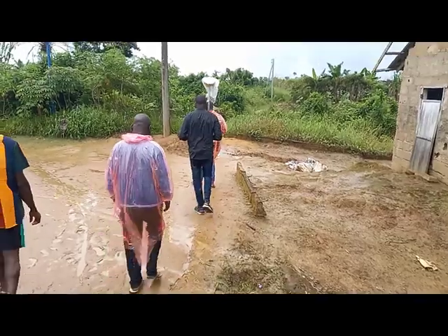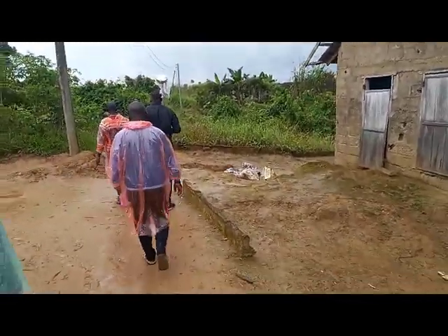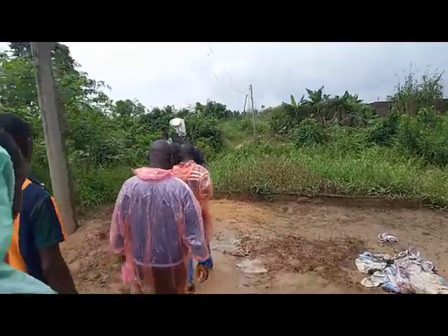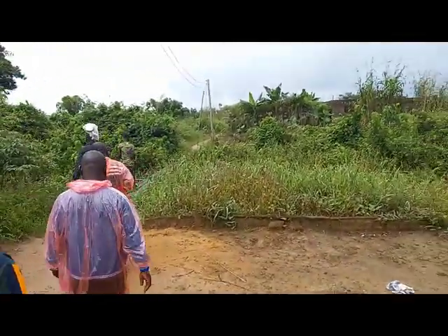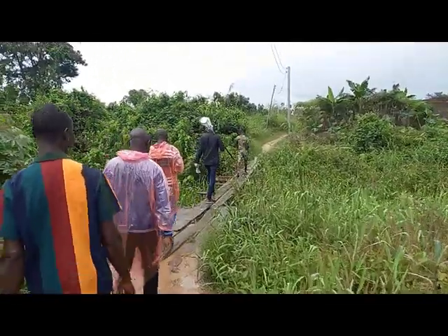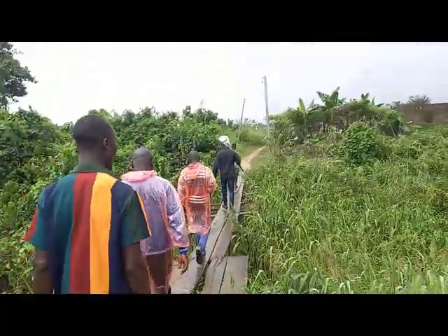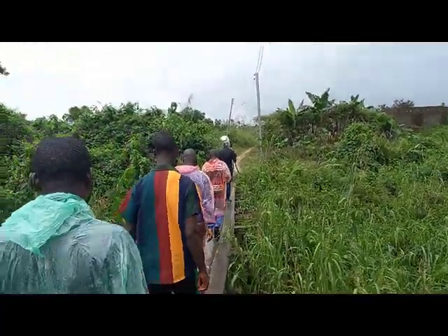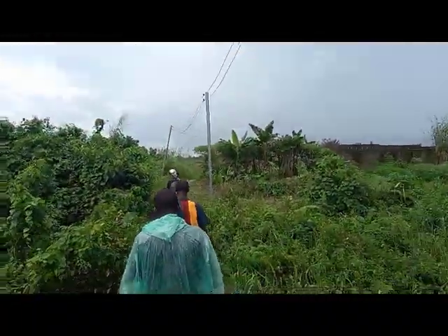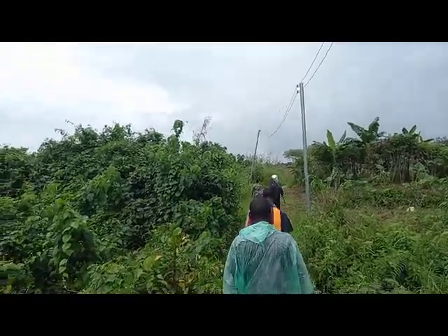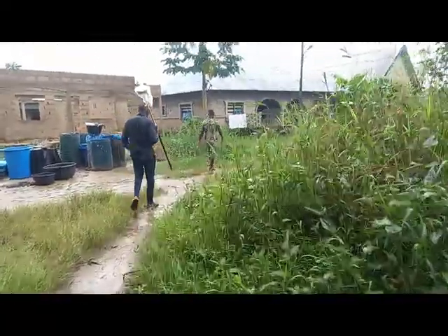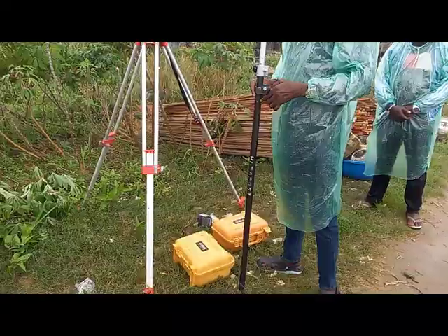So you see here when we're taking points within the community. Once you get to certain places, there are different distances that you can be taking points. So maybe you are taking points every 5 meters, every 10 meters, or say every 50 meters, depending on the level of detail you require. Also, there are different standards you can check online to know whether you are taking a 2.5-meter distance, 5-meter distance, 10 meters distance, or even 25-meter distance.